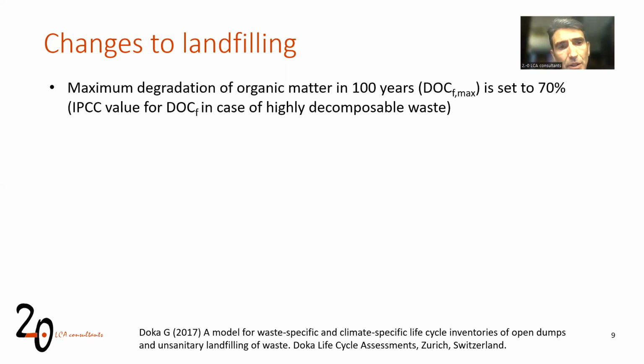What we said in version 5 is that the maximum degradation of organic matter in a period of 100 years in the landfill is 70%, considering that the landfill has the right conditions of moisture and temperature. This 70% value is the suggested value by the IPCC's guidelines on greenhouse gas inventories, and is the value they suggest for highly decomposable waste.